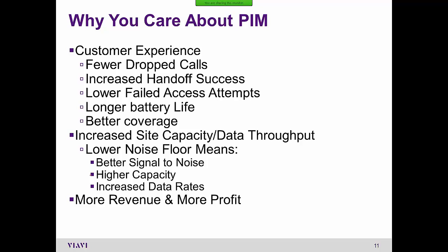And it used to be that all the technologies were voice. And voice has an awful lot of error correction in it and a lot of tolerance for higher noise floors, but data doesn't. Data simply will slow down, use slower modulation schemes that are less impacted by noise. So end users will see immediately differences in noise floors.